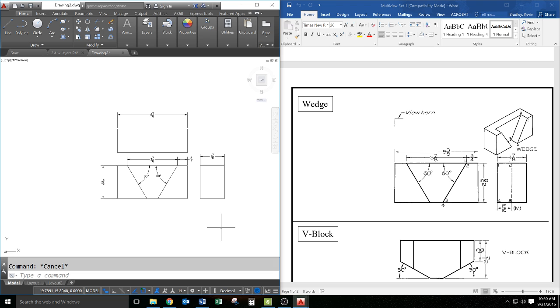As far as what the top view would look like, well, first of all, they have a line that's 15/16 over on the right view. Let's finish the right view first. So I'm going to do the same thing. Offset, 15/16, 15 divided by 16, and I'm going to offset this line 15/16.